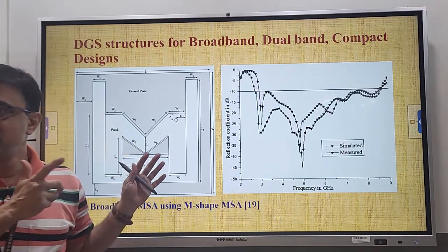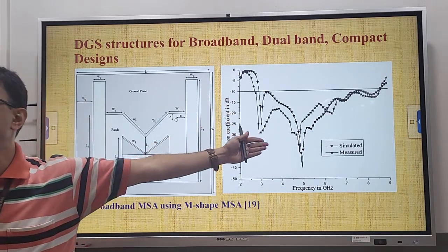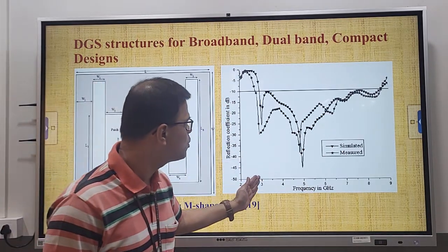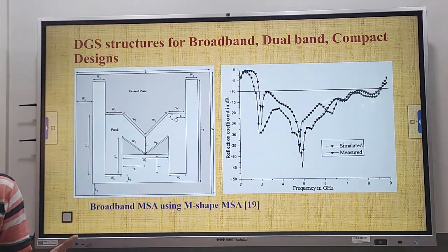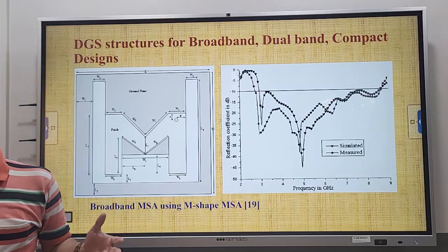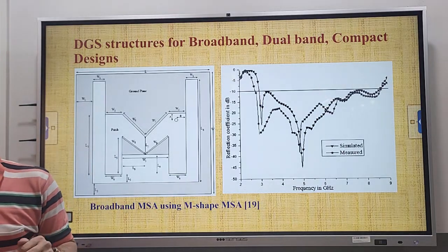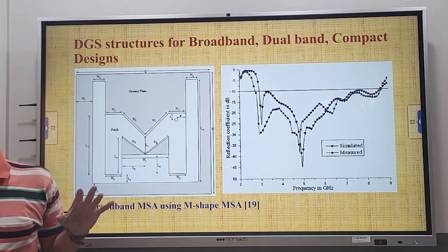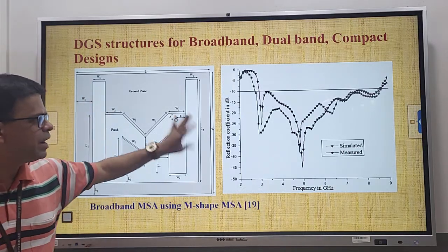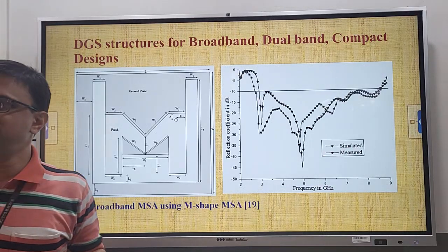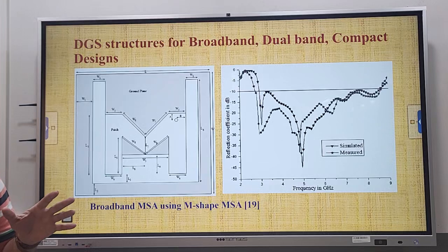Definitely the antenna idea is novel, because the bandwidth you get is really an ultra wideband configuration, from almost 2 gigahertz to around 9 gigahertz. So it is an ultra wideband design, more than 100% bandwidth. That is a beautiful configuration. But why is that broadband response obtained? Which modes are contributing to this wideband response? That needs to be assessed. So again, this is a wide open topic. One can look into this to come up with an original explanation for understanding this wideband response.